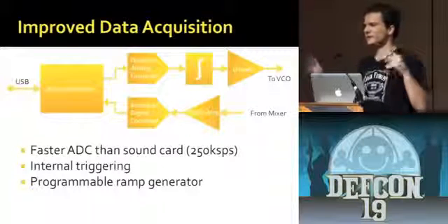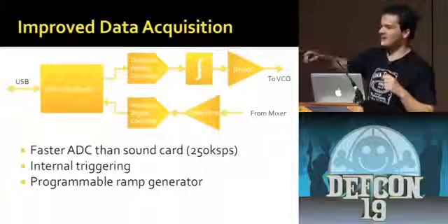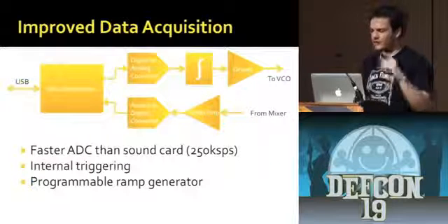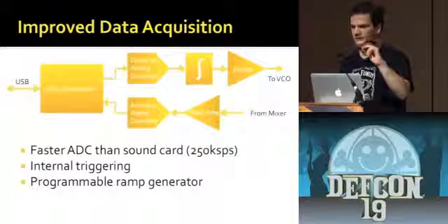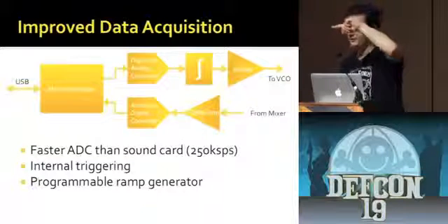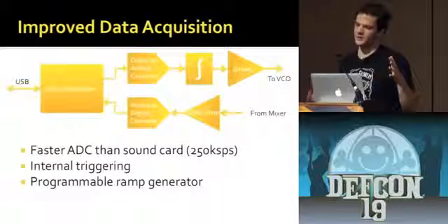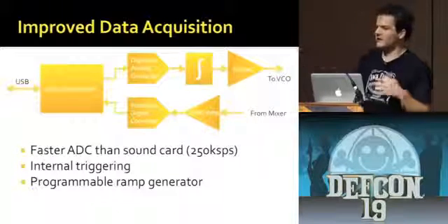And if you remember your signals and systems, that continuous line turns into a ramp, and we can control the speed of that ramp. The reason we're not just directly generating the ramps is that if you ever looked at how a DAC outputs a signal, every time you switch it, it jumps to the next level a little bit. It doesn't smooth it out. So we could filter the hell out of it and it probably wouldn't work, or we could just generate a flat signal and then in analog we make the ramp.